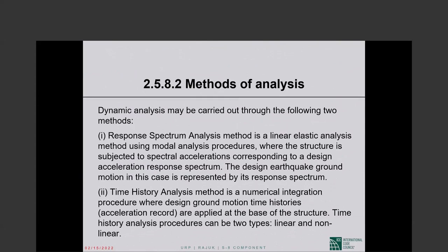The modal response spectrum analysis is when a structure vibrates, let us say under earthquake ground motion. Remember, the foundation starts moving every which way all of a sudden in an earthquake. The remainder of the structure, because of inertia, cannot readily follow the movement of the foundation. It stays behind, and then tries to catch up with the movements of the foundation. That sets the rest of the structure in vibration.